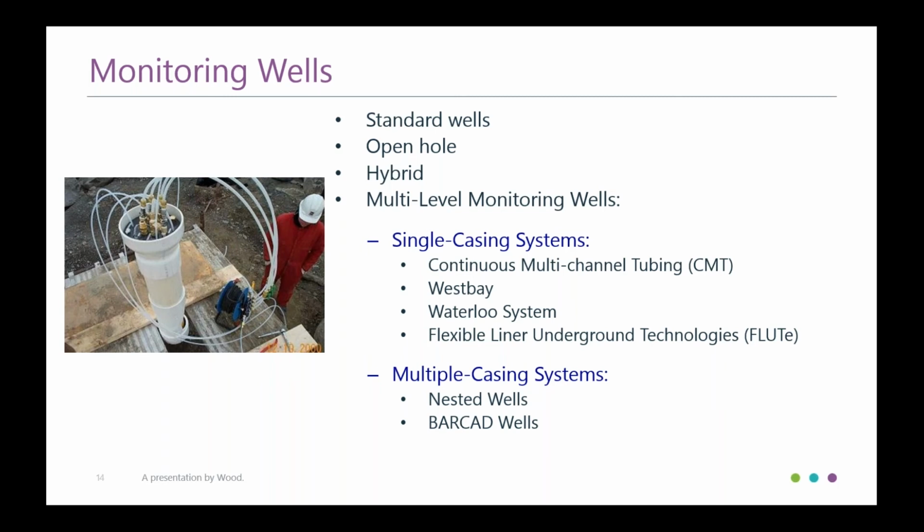If you leave an open hole, there are issues. Contaminants can migrate more easily. You don't know where the sample you have is coming from if you don't have the fractures defined. But there are reasons that people leave them. You can put in passive diffusion samplers, things like that, to start understanding more of the bedrock structure and where the contaminants are.